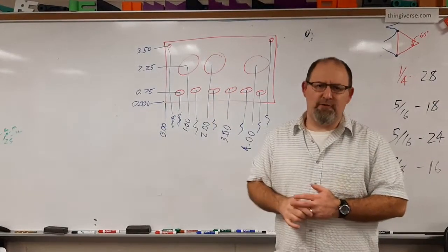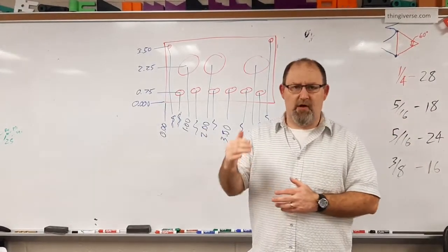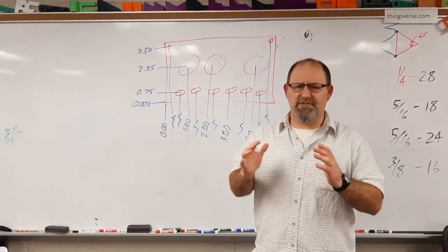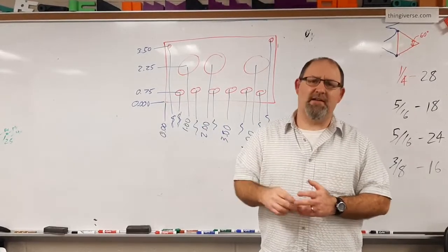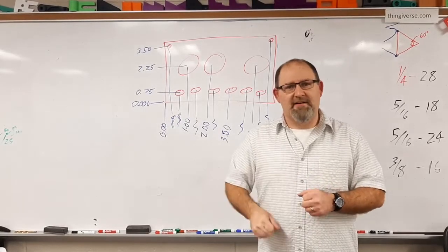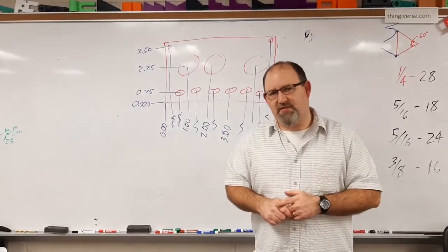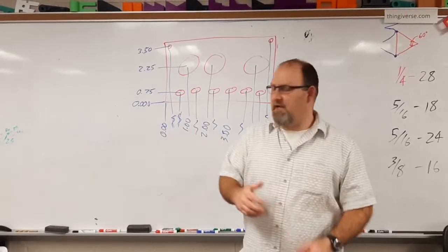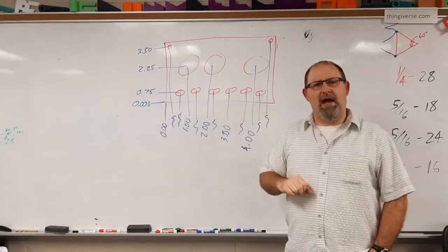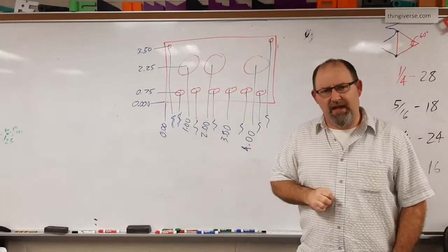And by the way, I'm talking about like if you pluck a hair and slice it into 10 pieces, that's about 2/10,000ths of an inch. Some machine shops can hold that tight of tolerance, which is super, super tight, but it costs a lot more money to do than somebody who's just running a handsaw, cutting bar stock, for example, where it might be plus or minus an eighth of an inch. So just something to keep in mind as we talk about these accumulated tolerances and how they interact.